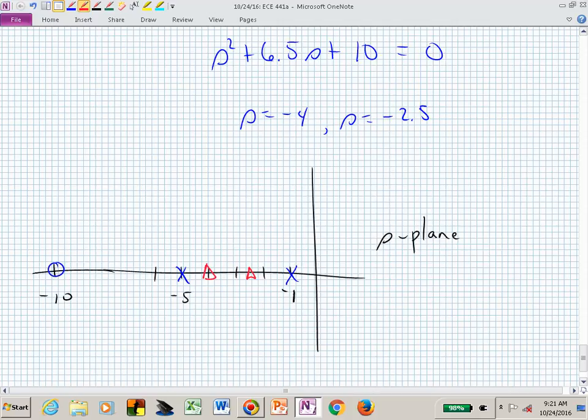But they're not necessarily going to meet midway because we have this additional information for poles and zeros beyond just the -1 and the -5. If we just had two poles and nothing else, they would collide right at the midpoint. But you can see that for cranking up to 1/2, they didn't even move at the same rate, did they? -1 went quite a bit further than the pole at -5 moved in.